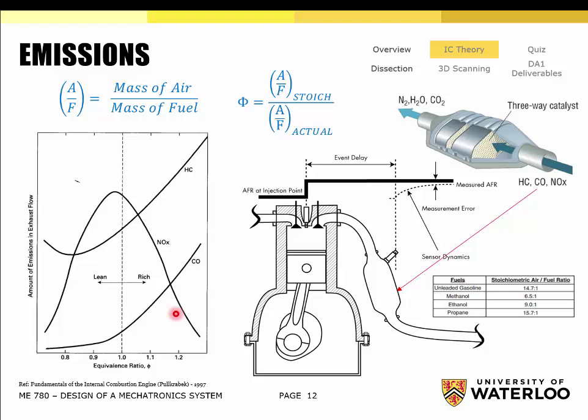Well, we're totally the opposite. So what we do is we implement what's called a three-way catalyst, and all that is, is a medium by which we can facilitate full combustion. If it never happened inside the cylinder, all of this reaction can continue to occur within the exhaust. We're providing this very porous surface area, and a lot of it, so that effectively everything can get converted into CO2 and H2O. Those are the natural byproducts of the internal combustion engine reaction. CO2 and H2O are not harmful, really, to the environment.